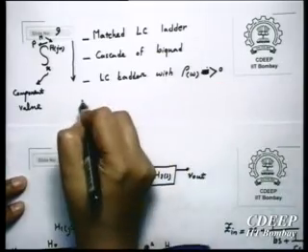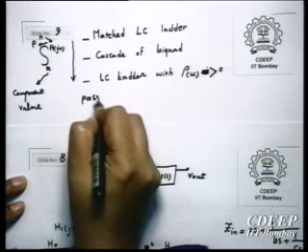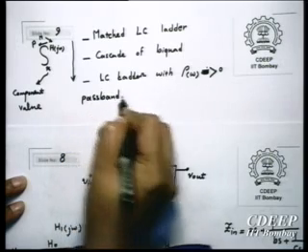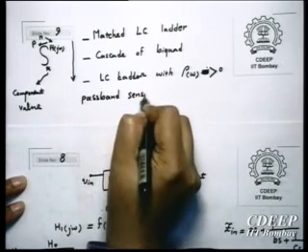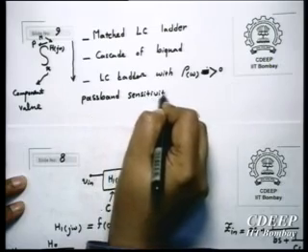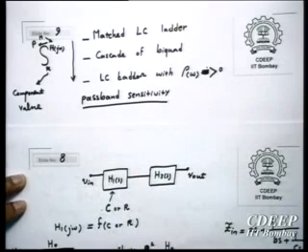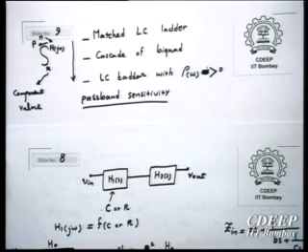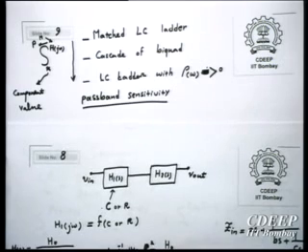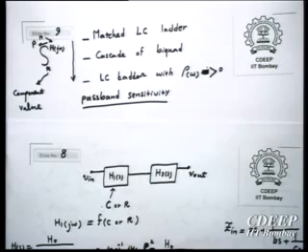So this is for the passband. If you are concerned about passband sensitivity, a matched LC ladder is the best implementation, and then simulate it, in the sense that you realize it with an SFG. However, if you are talking about the transition band, both of them have problems.